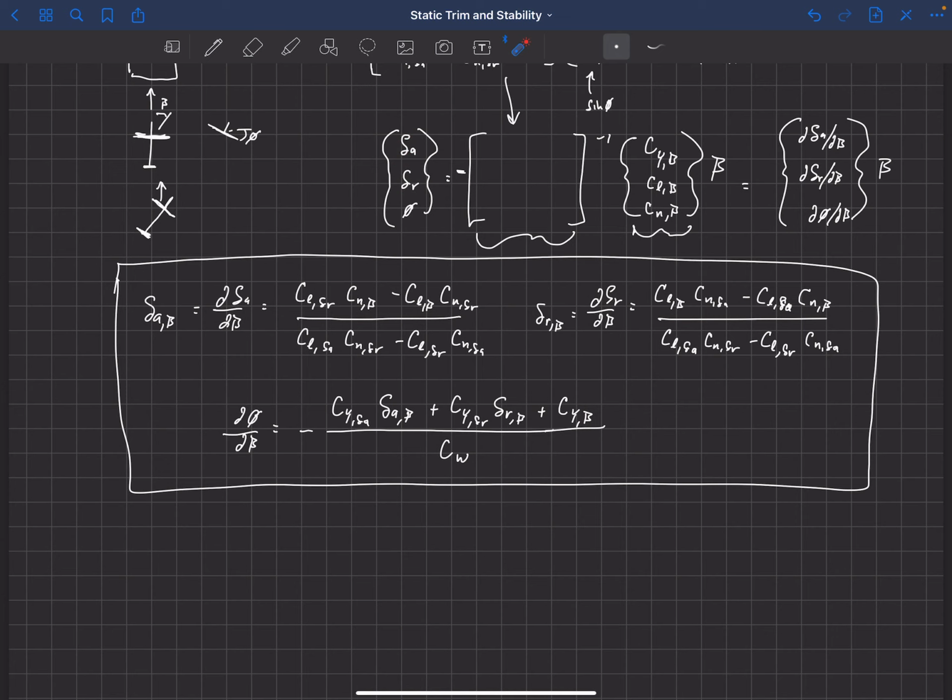So we're going to be limited in the side slip angle that we can handle because of our aileron design. This helps us understand what's going to saturate first and what we might need to change on the aircraft in order to give us larger side slip angles that we can trim to.